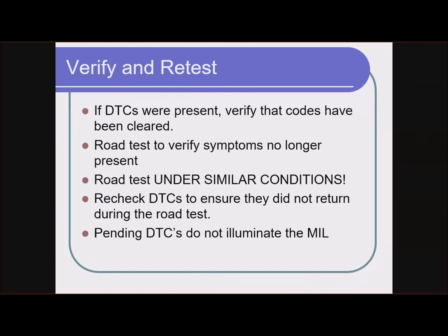So if the problem's at idle, you're going to verify the repair at idle. If you verified the symptom at wide open throttle, you're going to verify the repair at wide open throttle. If it only happens on a cold engine, obviously you want to make sure that it no longer happens on a cold engine. So the road test has to be under similar conditions.